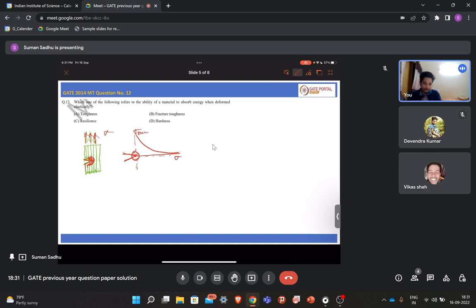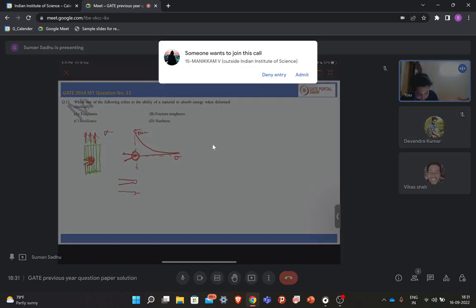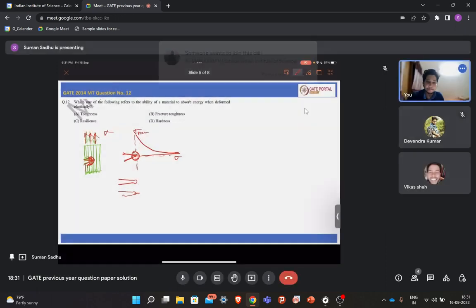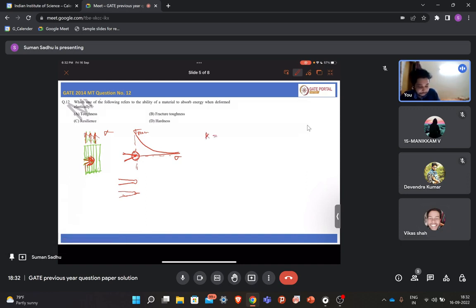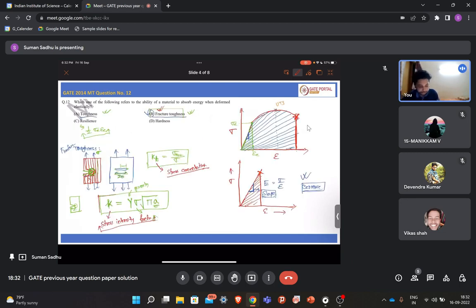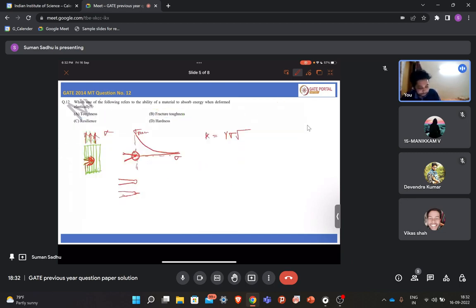If it is a plastic or ductile material, then first what will happen? That crack, because of the deformation, this tip will get blunted. Okay, and now when it crosses the limit, what will happen? Then again this blunted tip will also crack. So again it will form a micro crack. This way, basically, the crack will propagate. Okay, so once the limit is reached, then what will happen? This stress intensity factor, whose formula I expressed earlier, right? So let's say this is pi a.